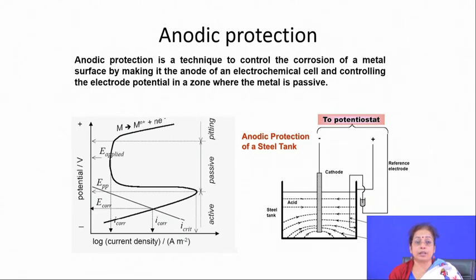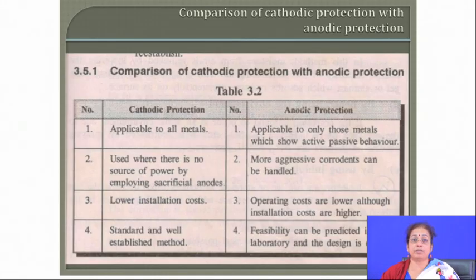So, this is the case of self passivation by the anodic current. So, you will find that the component gets protected. This particular anodic protection is applied only for those components which are very prone to corrode, and where there is formation of a passive film, and that passive film is highly protective in nature.